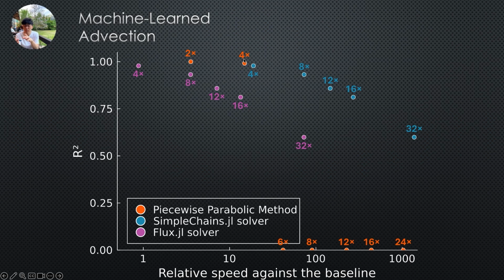We can also multiply the time step by 4 and get the same result. This suggests that we just had a relatively small time step to start with. But then if we try to multiply the time step by 6, basically accuracy goes to 0 and the model doesn't really run at all. And so this is what will happen when you do fluid dynamics simulations, right? If you have a time step that's too long, it just doesn't work.